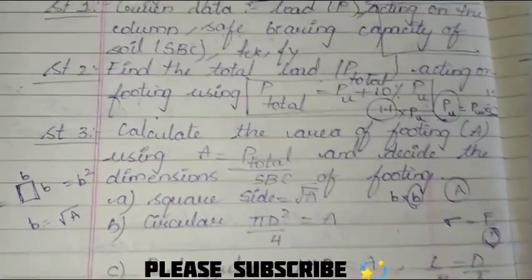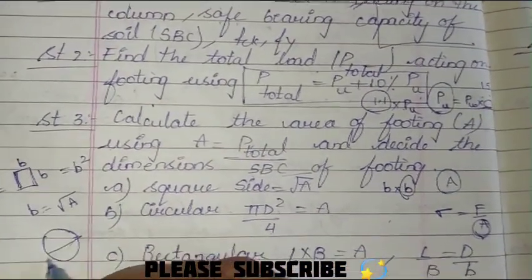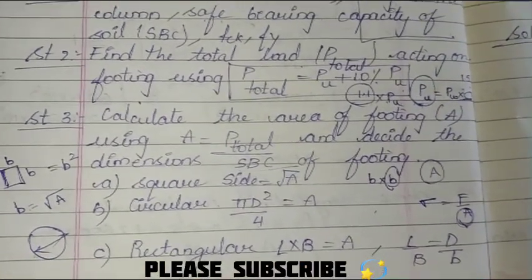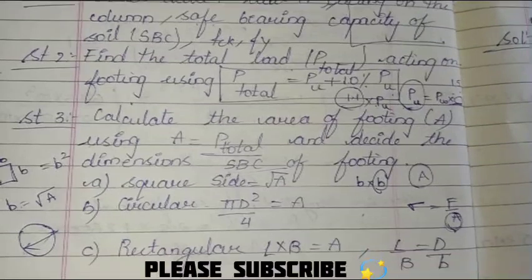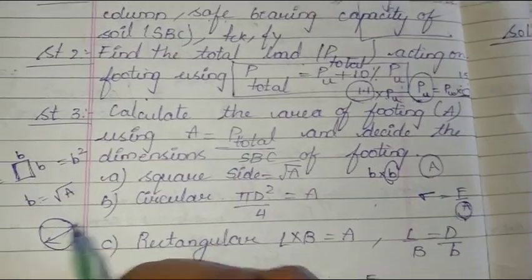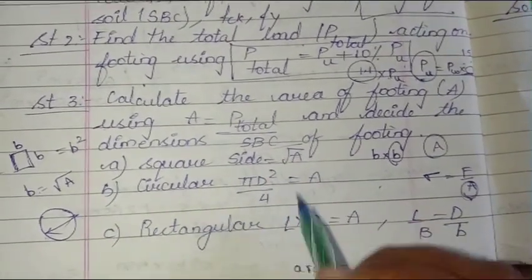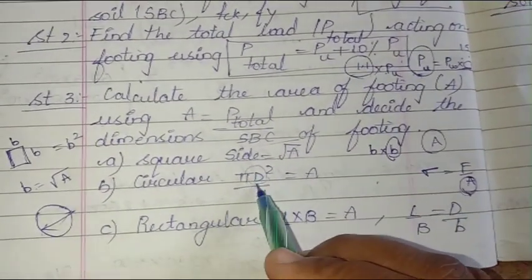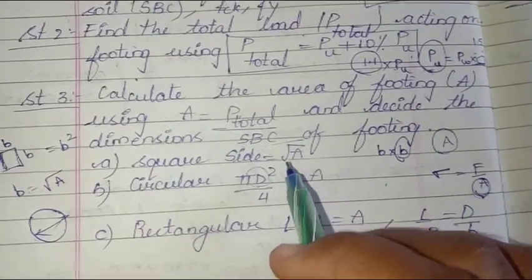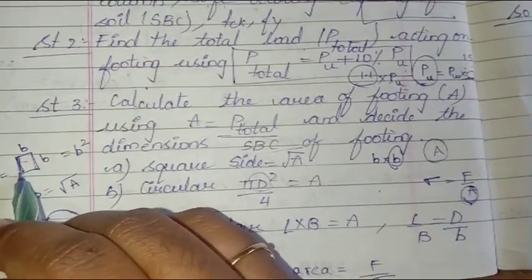And we know the circular area is nothing but pi d square by 4, where d is the diameter of the footing, the column. Whatever the load that is acting, for that we are deciding this footing. So if we want to provide a circular footing, substitute in this, and you will get the diameter of the footing. In this, if you substitute the formula, you will get the square side. Whatever the side of the footing is, we will get it.